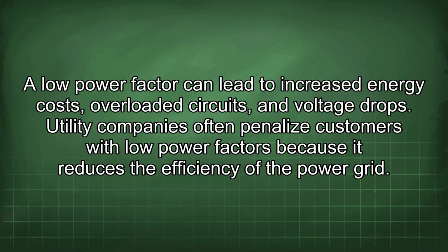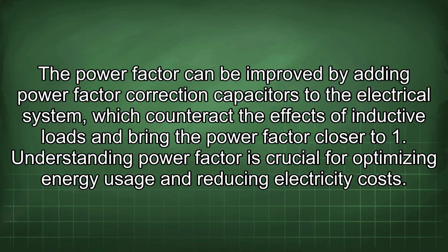A low power factor can lead to increased energy costs, overloaded circuits, and voltage drops. Utility companies often penalize customers with low power factors because it reduces the efficiency of the power grid. The power factor can be improved by adding power factor correction capacitors to the electrical system, which counteract the effects of inductive loads and bring the power factor closer to 1. Understanding power factor is crucial for optimizing energy usage and reducing electricity costs.